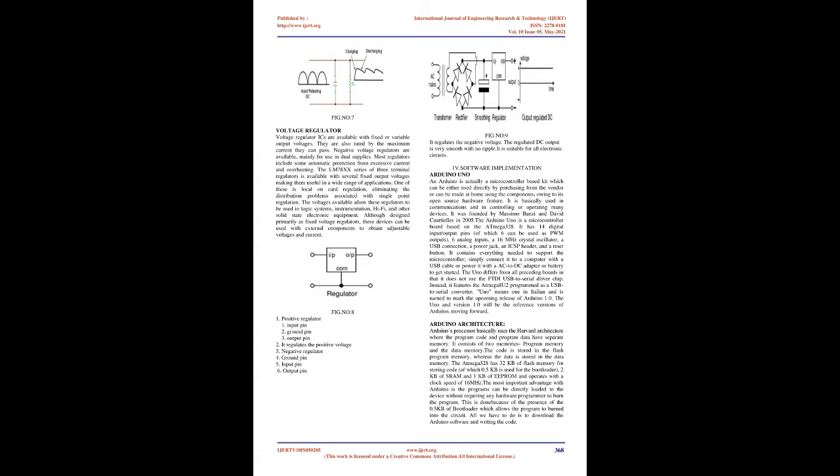Filter. A typical power supply filter circuit can be best understood by dividing the circuit into two parts, the reservoir capacitor and the low-pass filter. Each of these parts contributes to removing the remaining AC pulses, but in different ways. Electrolytic capacitor used as a reservoir capacitor, so called because it acts as a temporary storage for the power supply output current. The rectifier diode supplies current to charge a reservoir capacitor on each cycle of the input wave.